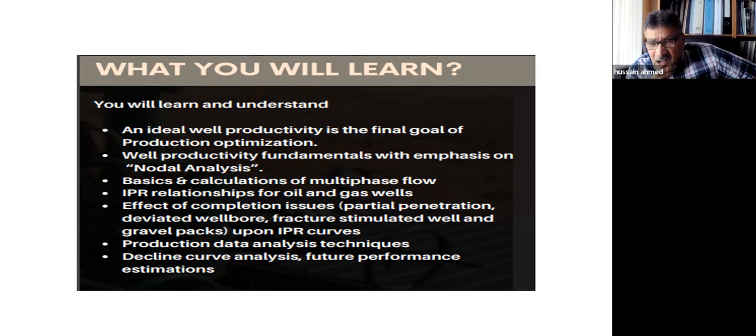We will talk about nodal analysis, which is very well known in choosing the right size of the production tubing, and also the relationship between what I call IPR and OPR, inflow performance relation and outflow performance. That's the idea of nodal analysis. We used to teach it by a graphical way anyway. Nowadays, people use computers or sometimes software to get a good idea. We do calculation of multi-phase flow as well. The IPR I explained to you. You will have some good examples, especially on the Vogel equation.